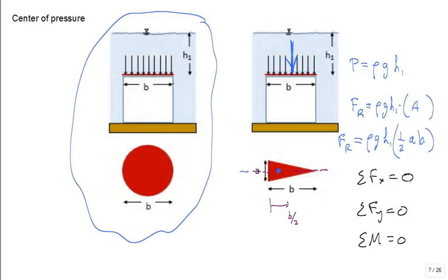Now, I know for 3D, you can have 3 force equations and 3 moment equations. But in 2D, just think 2 force, 1 moment equations, okay? Okay, and you think about moments about a point in 2D. In 3D, you think about moments about lines or axes. So that's how you got it. You got it from that principle, didn't you? Mm-hmm.